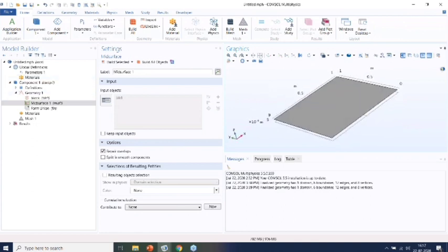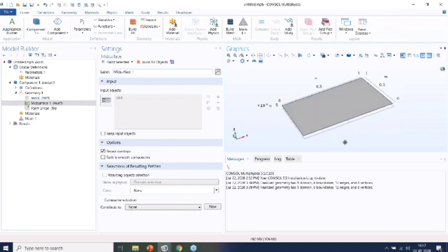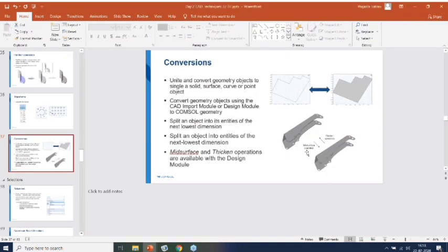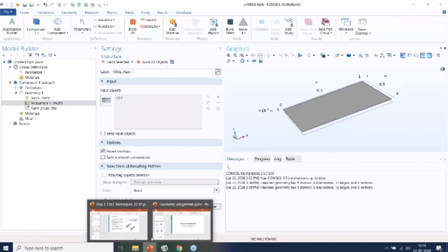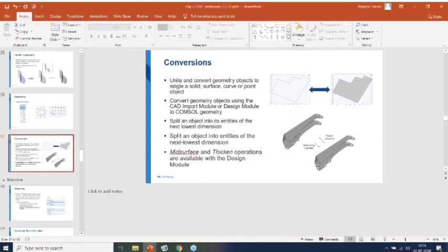Now, if you have a surface itself and you want to create a 3D object, for such regular types of geometries and surfaces, you can directly create an extrude operation. That is, you can just extrude it in a particular direction. But if you have an object like this, wherein extruding in just one direction will not help you and would be quite a tedious process, because you can see that the shell will be present at various planes, so how would you extrude along one direction only?